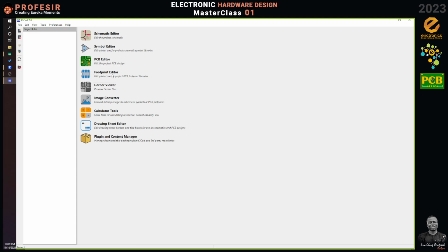If you want to create a PCB footprint, now later I would explain the difference between a footprint and all those kind of stuff. Is that okay? So probably let me just do it right now. So the library schematic editor, that is where we'll be creating our schematic. If you want to do simulations with Spice and generate our BOM, bill of material. BOM stands for bill of material. This is where we do all that.